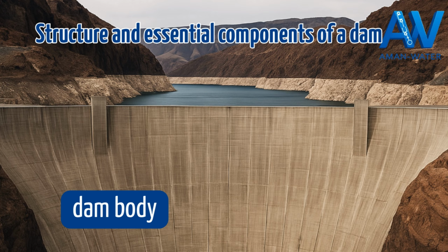In a gravity dam, the thickness of the concrete absorbs the force. In an arch dam, geometry transfers the pressure to the rock abutments. In an embankment dam, resistance comes from the compacted layers of natural materials capable of absorbing ground deformation.